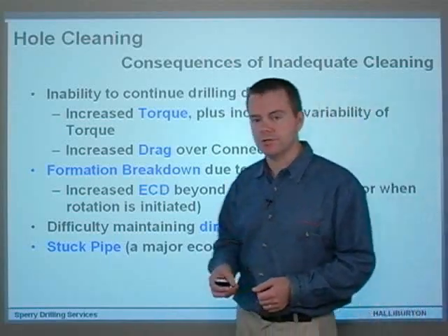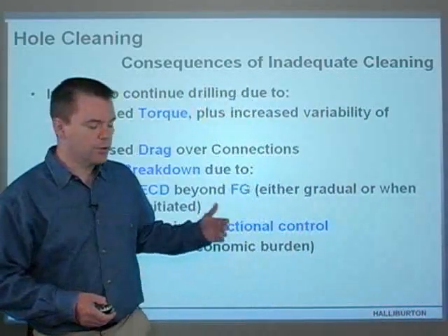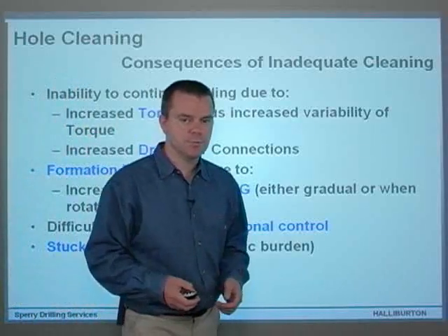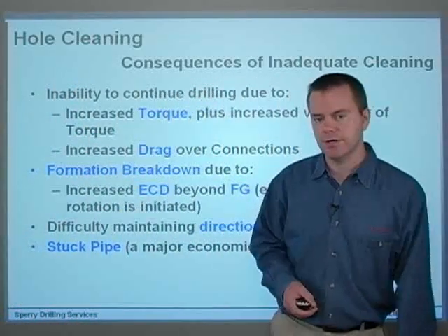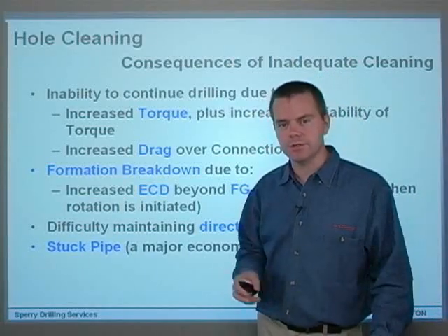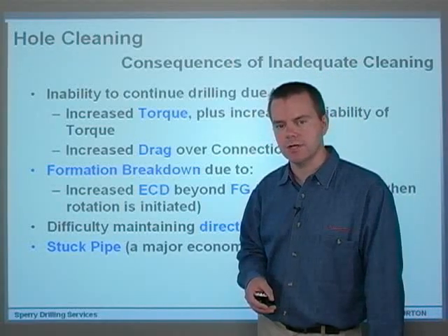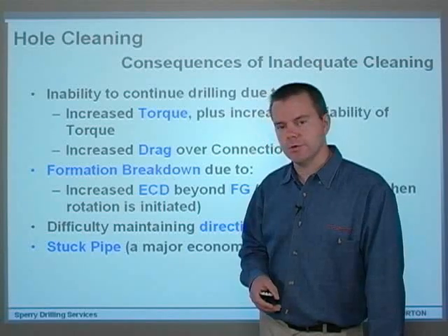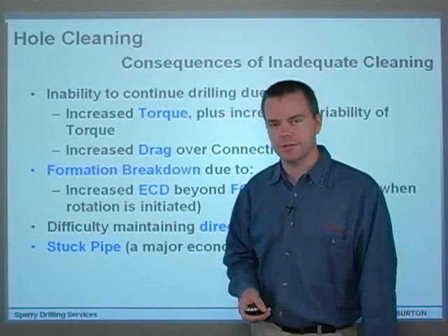Stuck pipe is a major economic burden, as it says here, on oil companies. That's why we get put on stuck pipe courses very often in the North Sea. For a long time it was one of the more common problems down the hole. And a lot of stuck pipe problems come from bad hole cleaning practices.